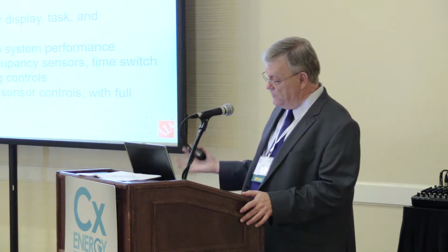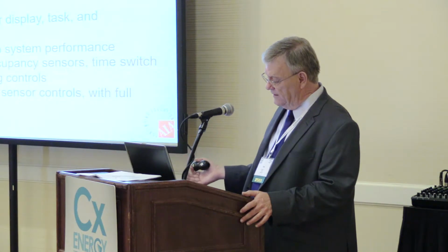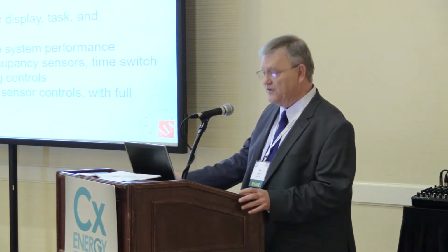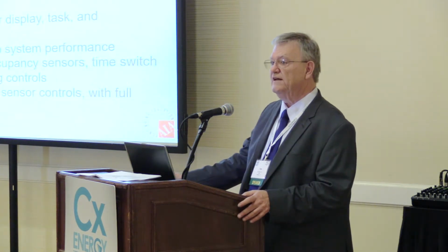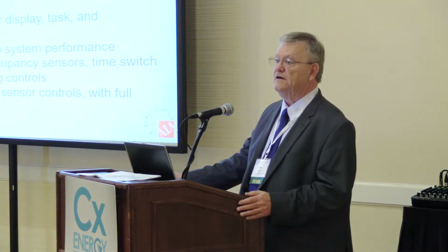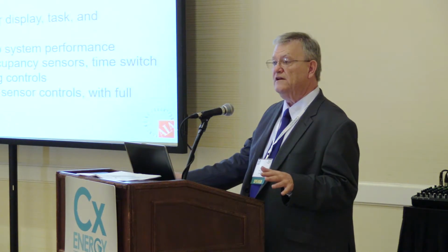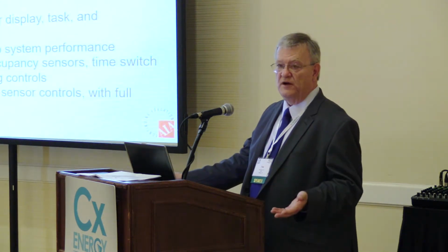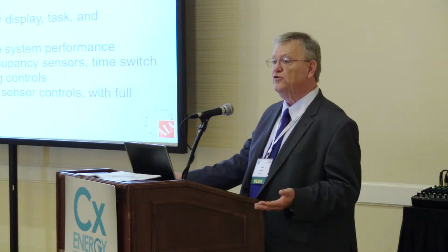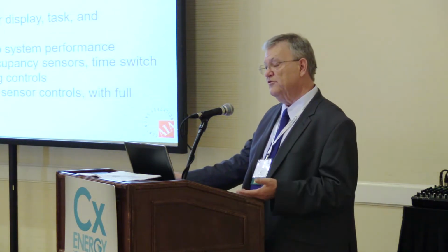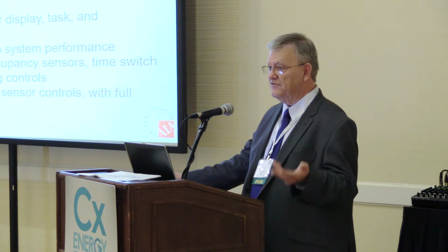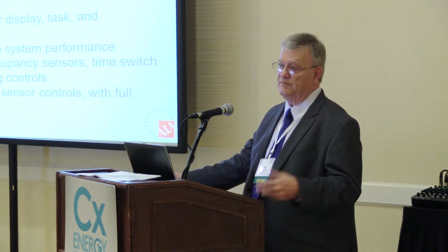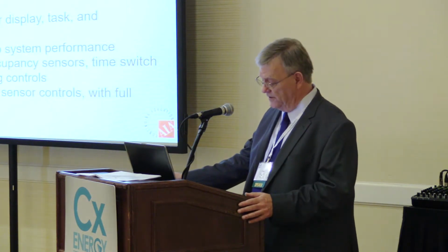ASHRAE requires at least 3 levels of daylight lighting. This actually, I think, is how the codes bias their selections toward LED lighting as opposed to fluorescent. There's a general view that fluorescent lighting is about as efficient as it will ever be, that it's been around for decades. We're not going to see improvements in its efficiency, whereas the belief about LED is it's still got a lot of headroom and can probably easily double in efficiency maybe before it starts to get close to the theoretical limits.